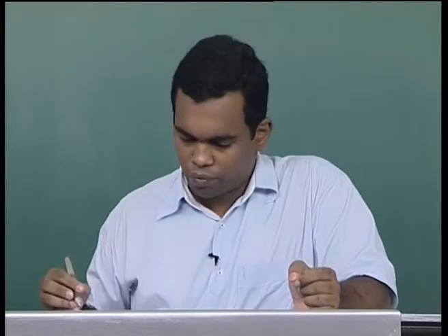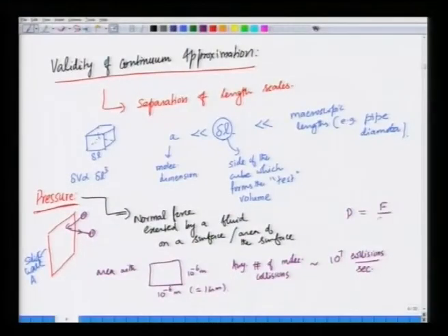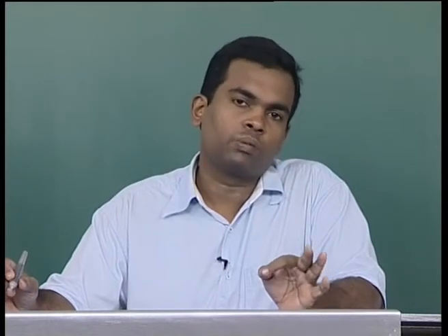So, when you define pressure as force divided by delta A, in the limit as delta A goes to 0, what this means is that as you decrease delta A to a smaller area, you will still find the value of the pressure to be uniquely defined. Even if you change the probe dimension, as long as you are not encroaching on the molecular scales, you will still find that the pressure is uniquely defined and it is independent of the test area.